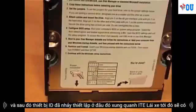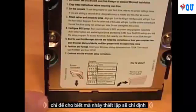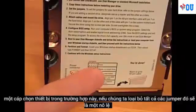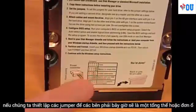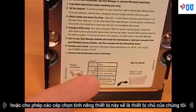Somewhere on the IDE drive there will be a legend or some indicators to indicate which jumper setting will specify the device as a slave or a master device or a cable select device. In this case, if we remove all jumpers, that would be a slave device. If we set the jumper to the far right, that would be a master or single drive. Or if we set it on the third jumper, that will enable the cable select feature.